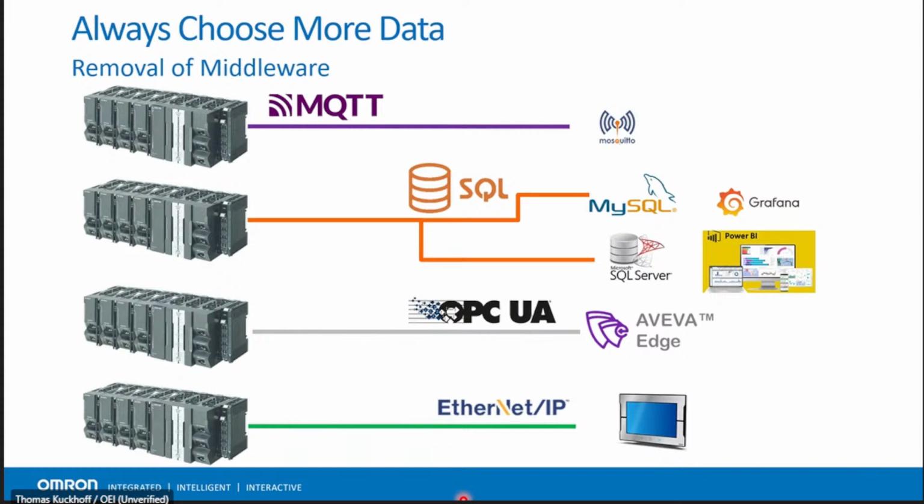And that's so important because typically there is a computer needed on the shop floor or factory floor to broker that data. But building that into the controller means a lot of teams can start transporting data to a third party out of the box. We do have function blocks for MQTT as well.